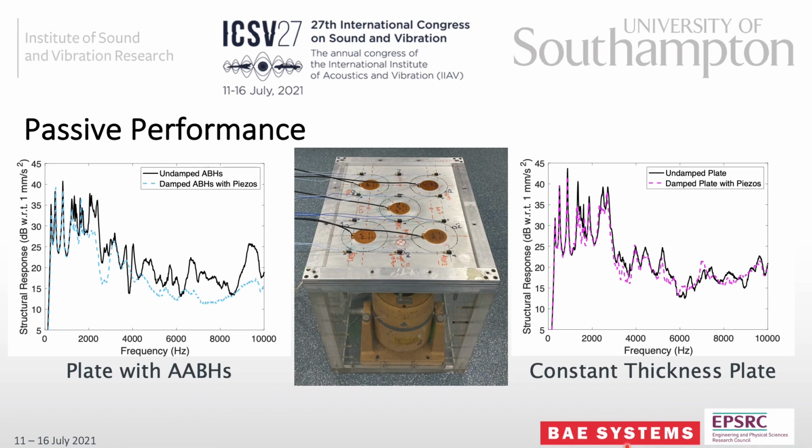If we start by looking at the constant thickness plate structural response, we can see that the addition of viscoelastic damping material and piezoelectric patches does not change the structural response much. At some frequencies you get a bit of damping, but in general the structural response is fairly similar to the undamped plate. In contrast to this, on the left, if we look at the plate with acoustic black holes, you can see that above about 2 kHz, roughly here,